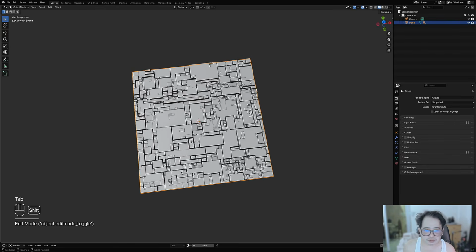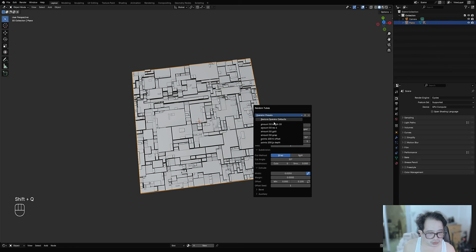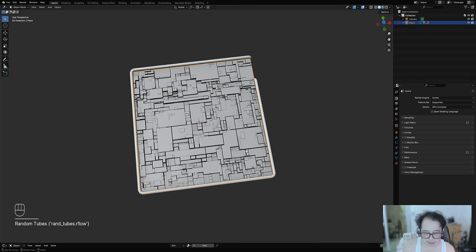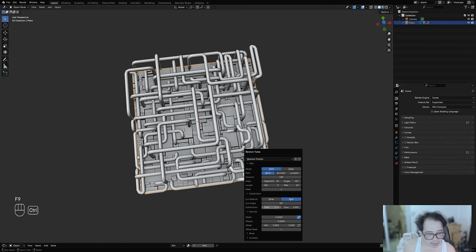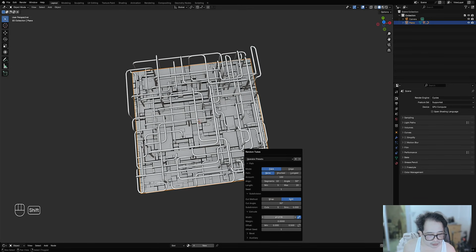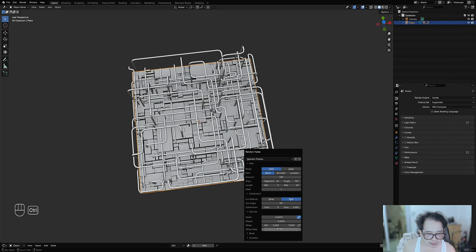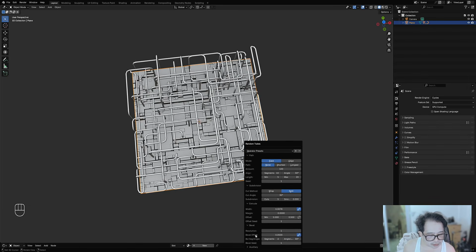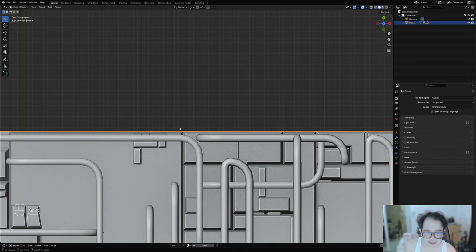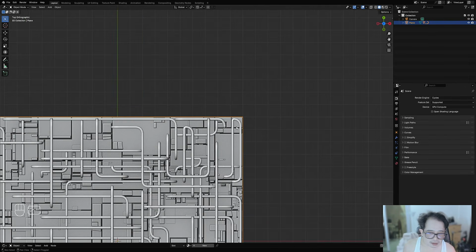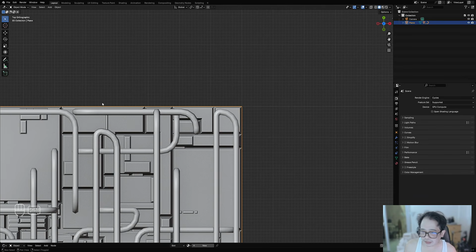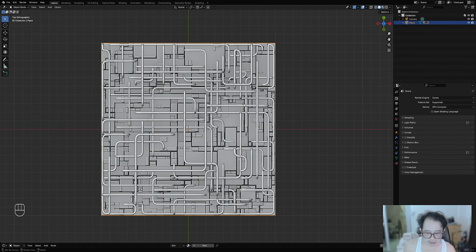And then I'm going to use random tubes and start off with the points 100 high offset and just increase the resolution, the width or the thickness of the pipe. Let's reduce that. And also, where's the segment? The bevel. So let's use 4 segments and introduce a margin so the tubes actually generate, some generate with some margin beyond the boundaries of the plane.